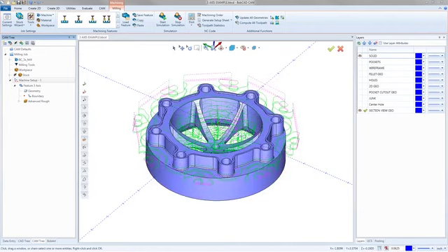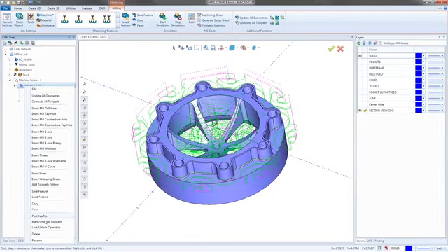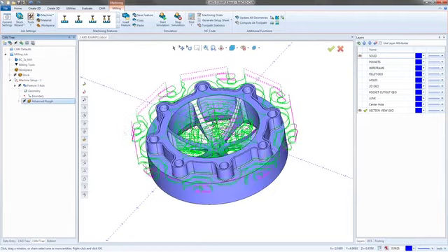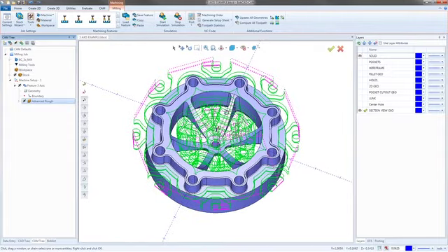So. All right, there's the tool path on there now. As fun as you could possibly make CAD-CAM software, right? Here we go. So I'm going to go ahead and blank this tool path out just so we can get kind of an idea of what's going on. So it's just going in, it's roughing, and right now I do have it cutting these pockets. If I didn't want it to cut these pockets, I'd have to create a piece of geometry that tells it not to cut those pockets. And that's exactly what we're about to create for the 3-axis finish pass.